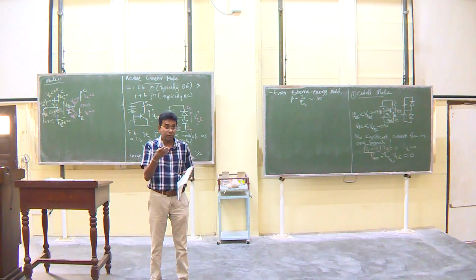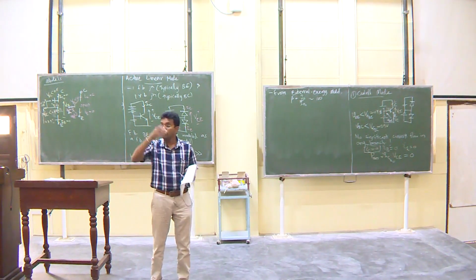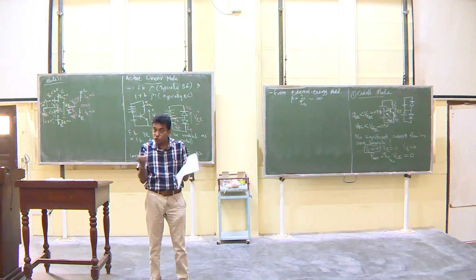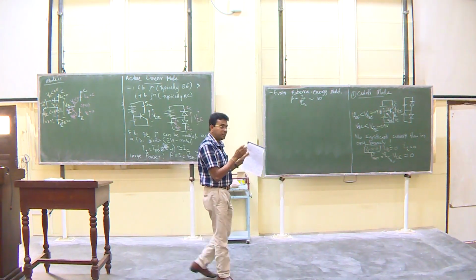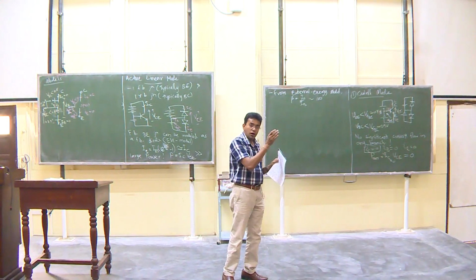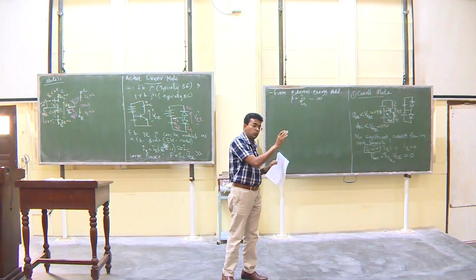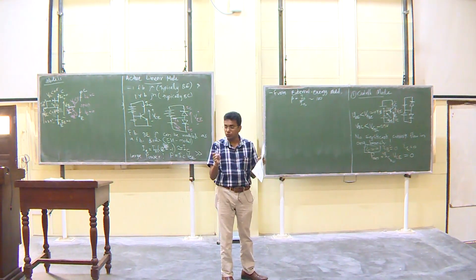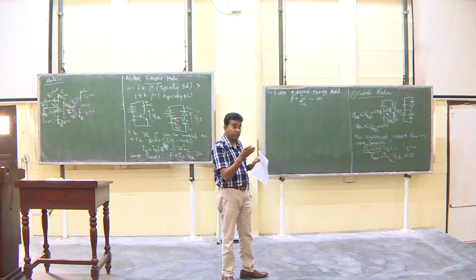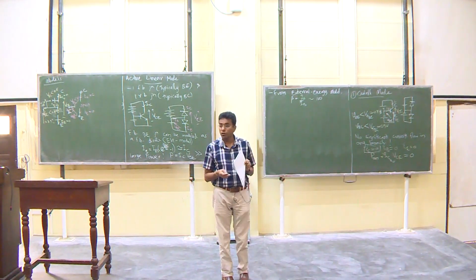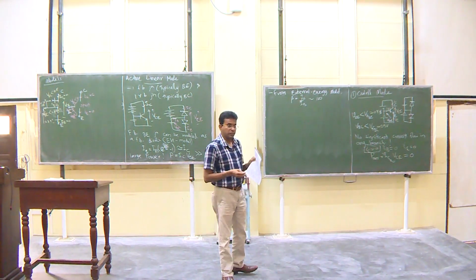If you change the temperature, this beta value may vary from 100 to 50 to 250. So, it is not a small variation, right. Therefore, we provide typical values, lowest value, highest value, the range in the data sheets. So, if the temperature varies, we have to take that variation of beta into account.